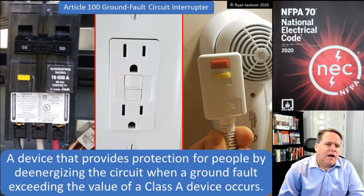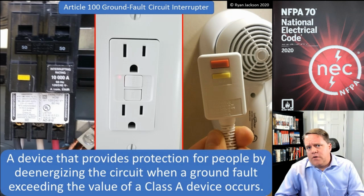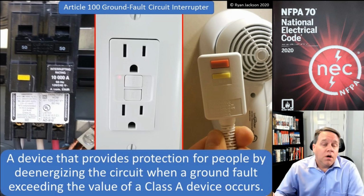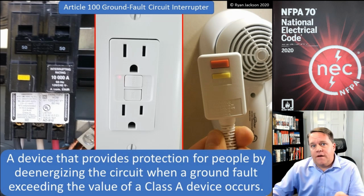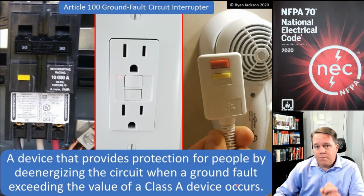Sometimes I'll have questions from people, and they'll say, Ryan, I've got a commercial kitchen. Do I have to have GFCI protection for the receptacles? Can I put in GFPE for the receptacles? And the answer is no. If the code requires GFCI, it has to be Class A because that's what the definition says. Class A is intended to protect people.